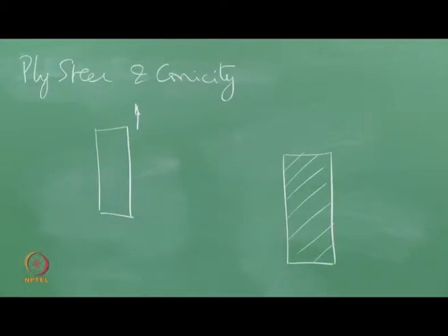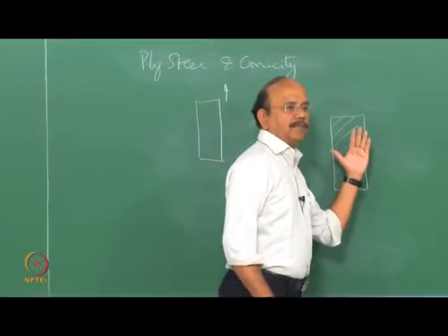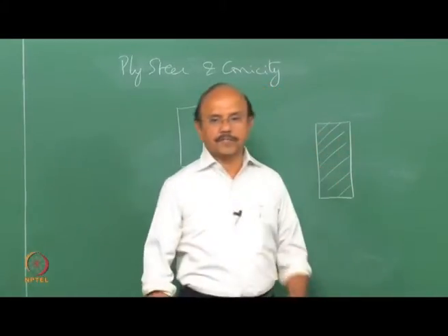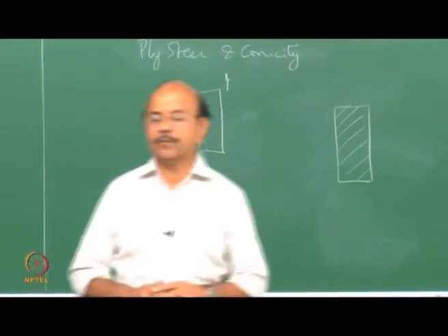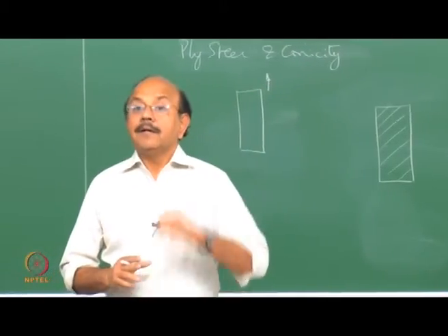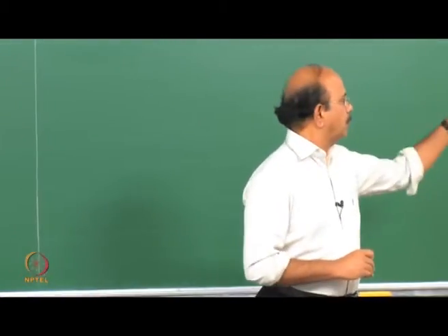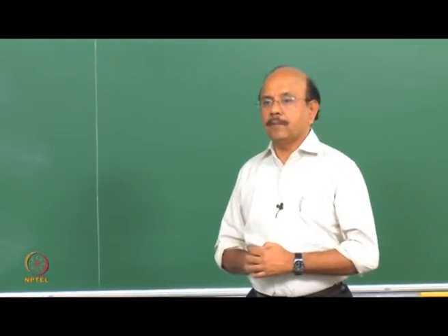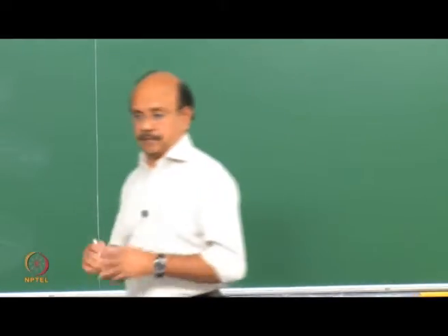And there will be another belt, where the steel cords run in different directions and so on. There's an angle to this. Let's not worry about exactly what the angle is. In other words, this whole belt bundle, the bundle which is just above what we call the body ply, behaves as a composite laminate.